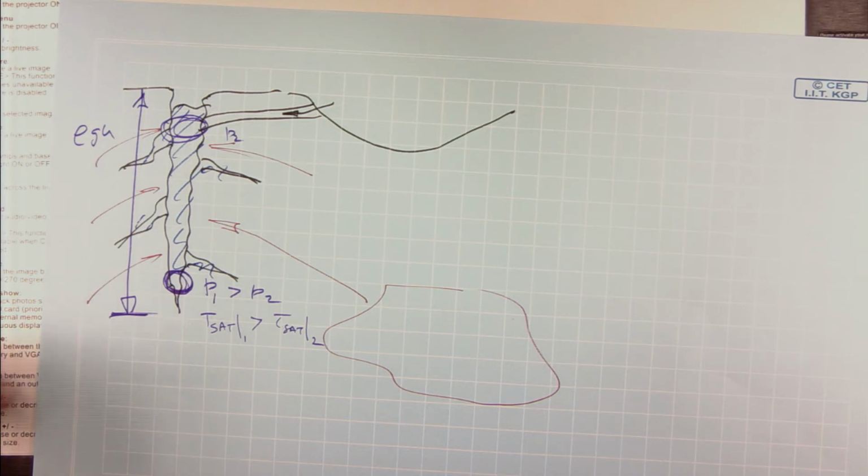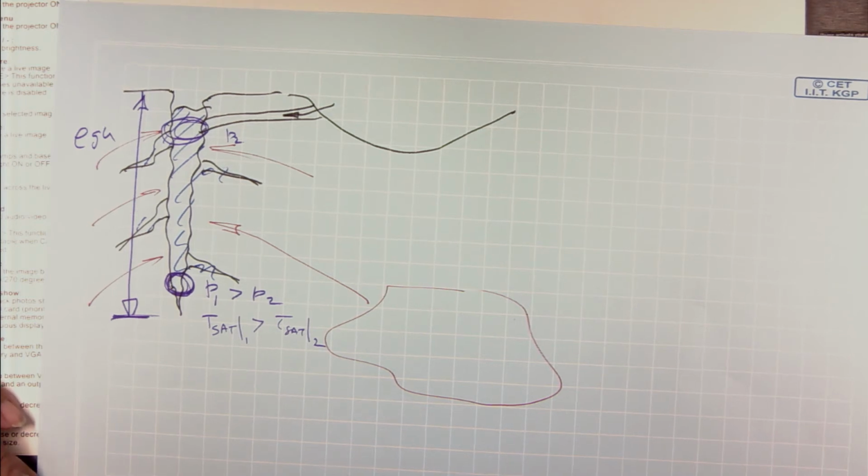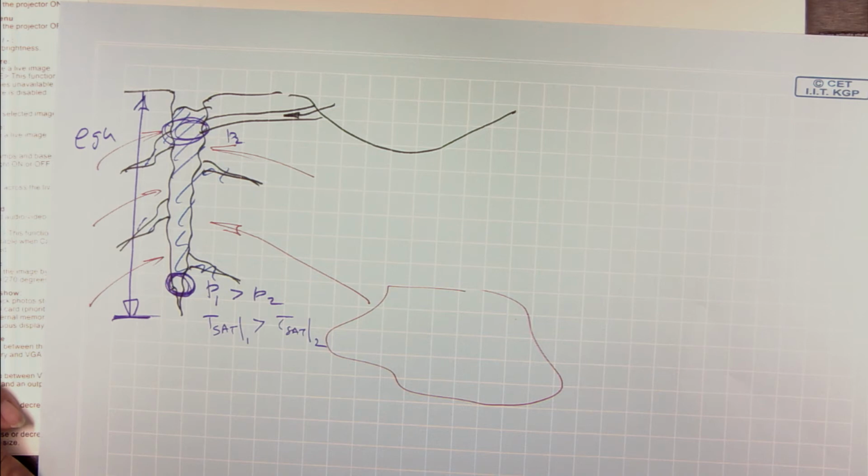Okay, and once that vapor bubble forms, it creates a shock pulse, and all that vapor wants to leave, and in that process it drags the whole mass of liquid and lifts it up as that steam is leaving the system, and that's when you get the whole water spout coming out. And once the steam leaves the system, the water is dragged out with it, the whole process repeats. Okay, so that's how a geysering instability occurs.